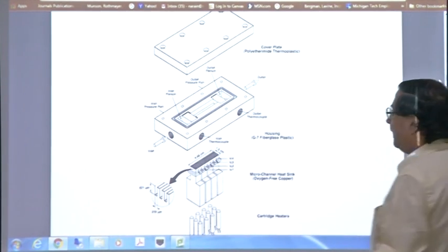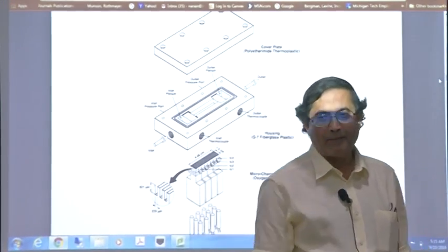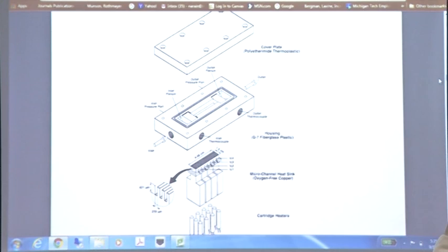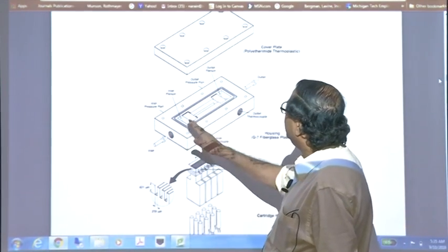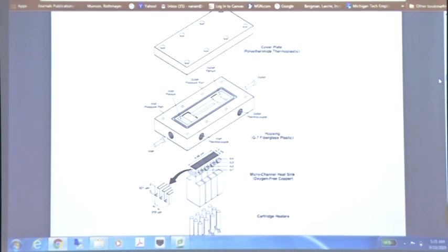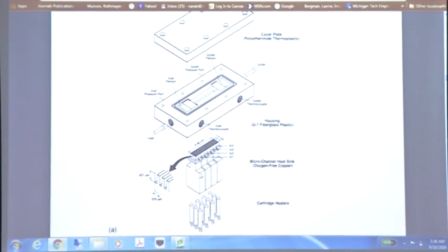So you have a high heat flux here, then you converge and all heat is going up, and so like a flow, you can go from 100 to 500 watt per centimeter square. So then you can electrically control the amount of heat that you're going into the section, and look at it from the top, a glass, sapphire glass or something. You have to make sure that these are leak proof. These are cartridge heaters inserted into the electric heaters, this wedge shaped electric heaters.